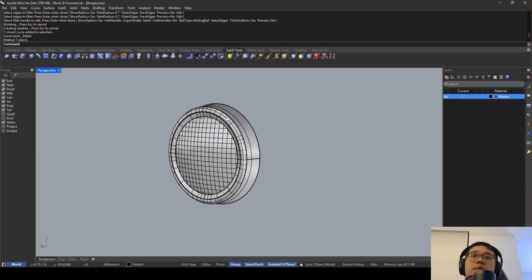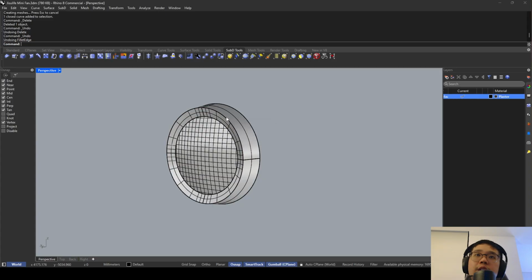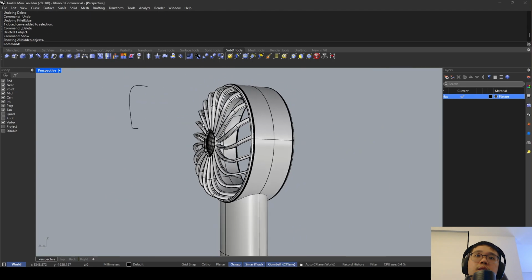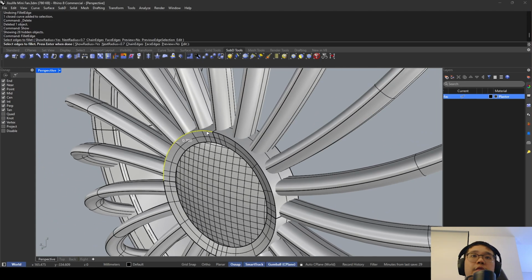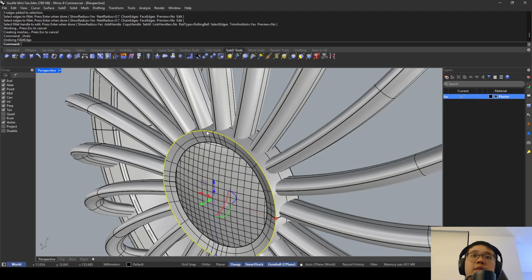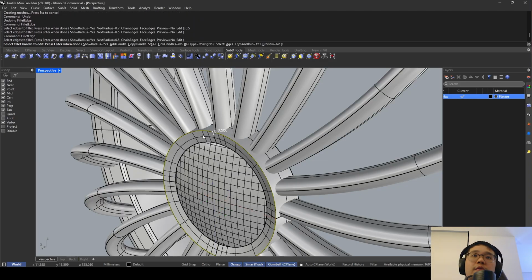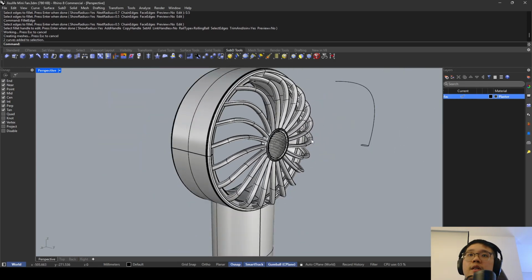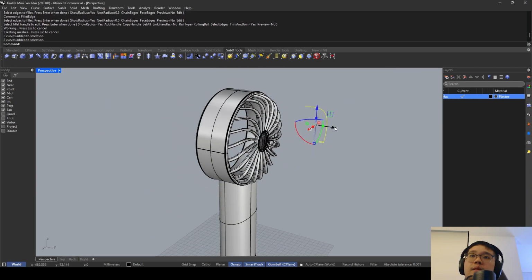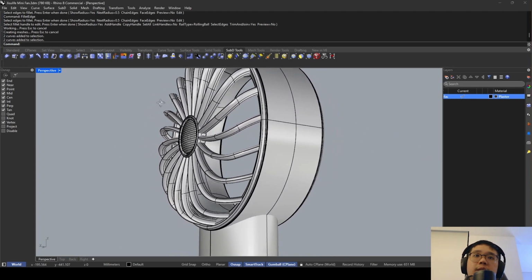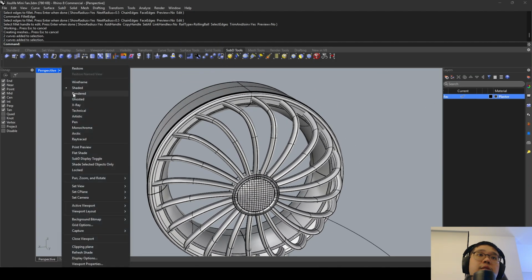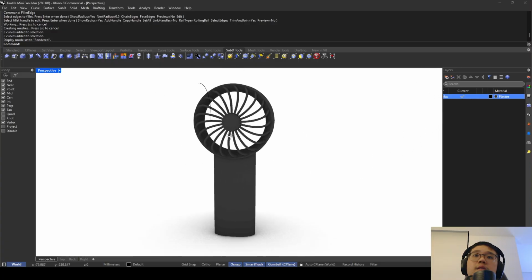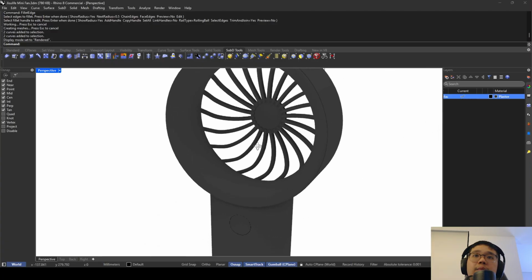Yeah. Hang on, I'm not gonna fillet this one yet. Now I can fillet it. Now I can fillet this. 0.7 is too much. Let's do 0.5. Yeah, perfect. Okay, I'm happy with this. Bring this another 50 mil. I'm happy with this. So, next step here. So that is the back part of the fan.